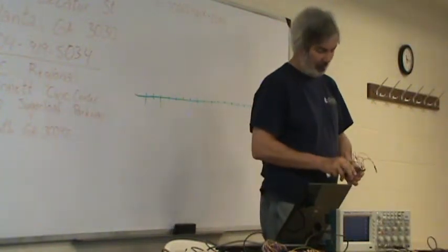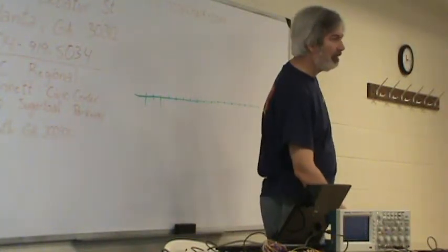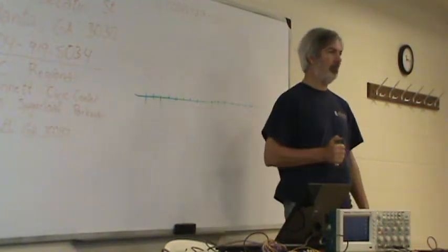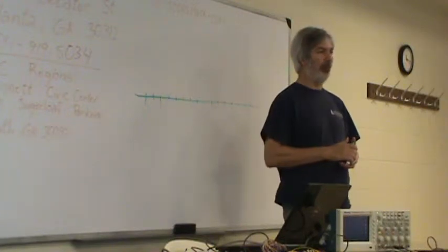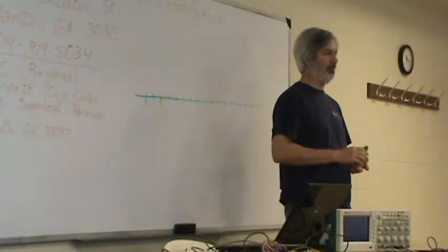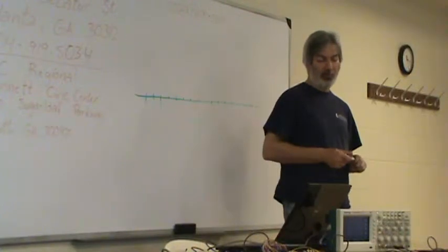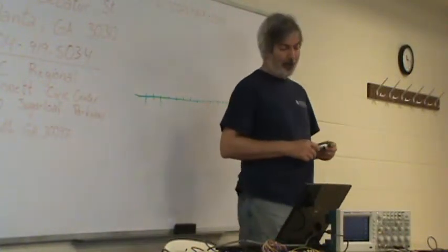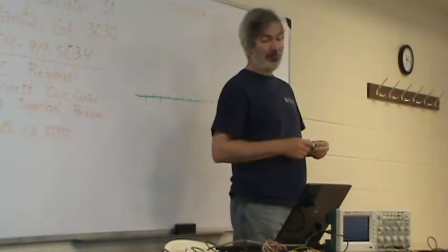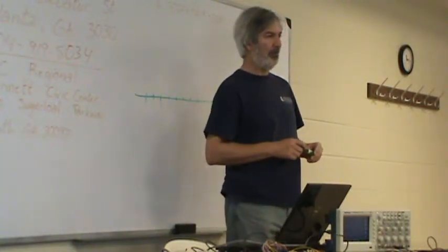Typically the switching regulators are a little bit smarter, and what'll happen is, instead of dying, they'll go into what's called foldback mode. And basically that's a fancy word for, it's going to drop the output voltage to keep from damaging itself, or it may simply shut off. And so an easy way to find out what's going on there is you measure the voltage. Now this isn't necessarily strictly a scope method. This will actually work with a meter as well.